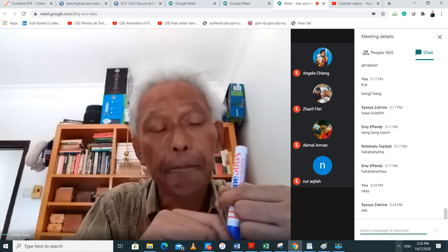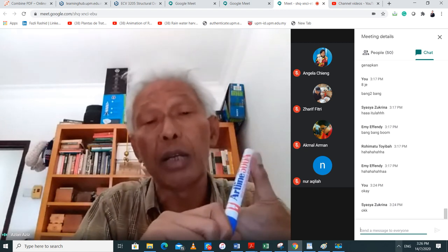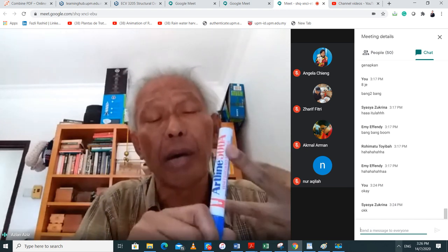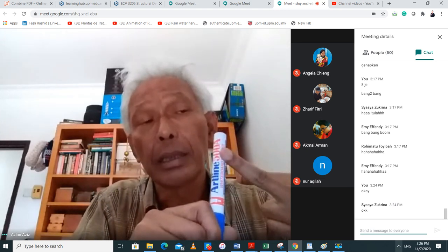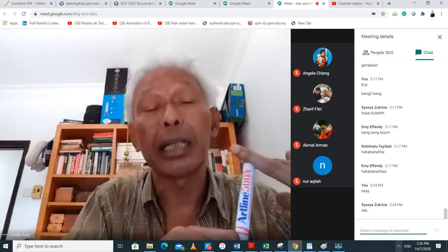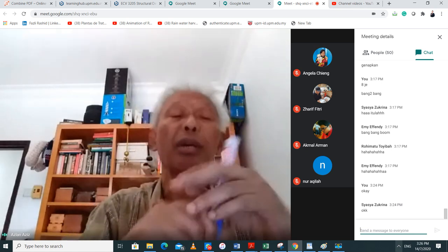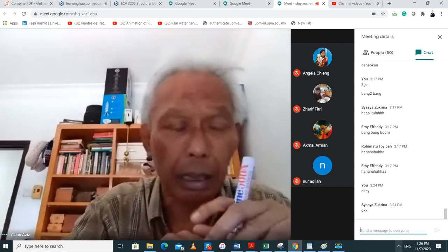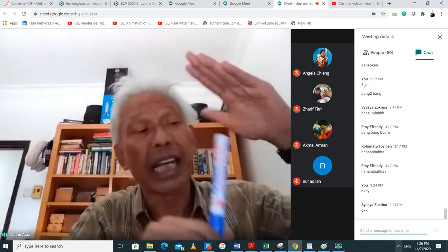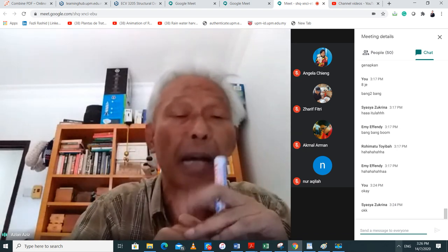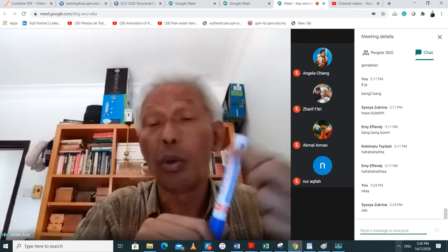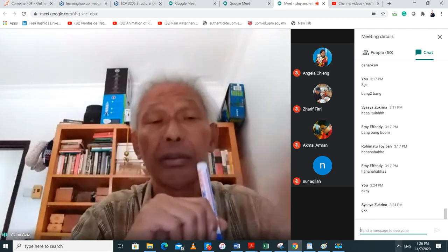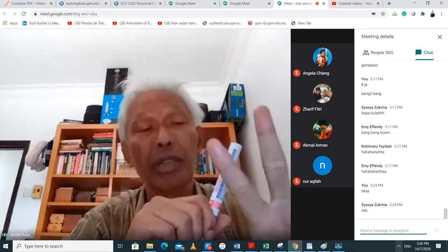All right. So the first one was a pile load test. The second one, you say, using the static load formula. The third one is, what was the third one? Use a dynamic formula. In other words, you bang it in. This only works if you install the pile using those dynamic methods. If you use a bored pile, where you just drill a hole and you put reinforcement and then you pour concrete into the hole, then you cannot use it. All right. So those three methods.